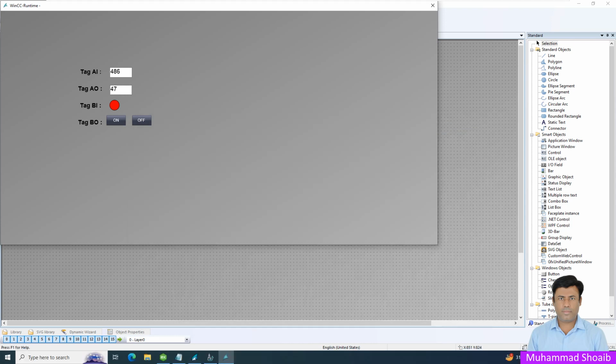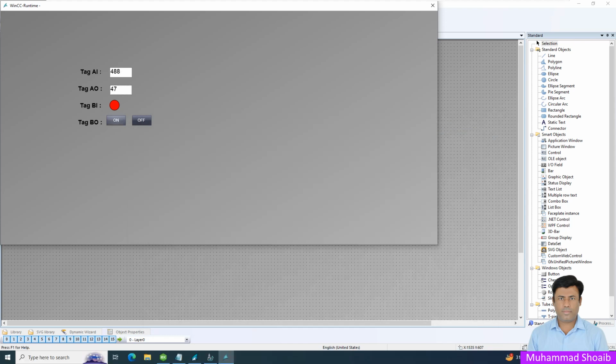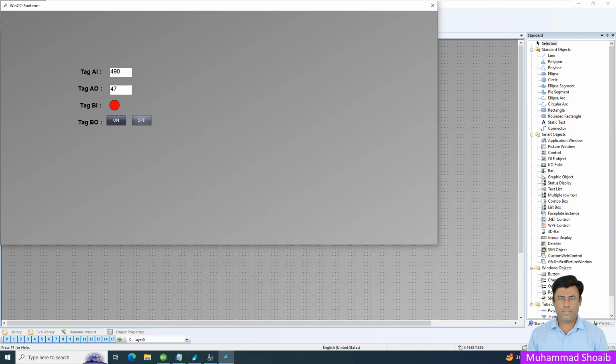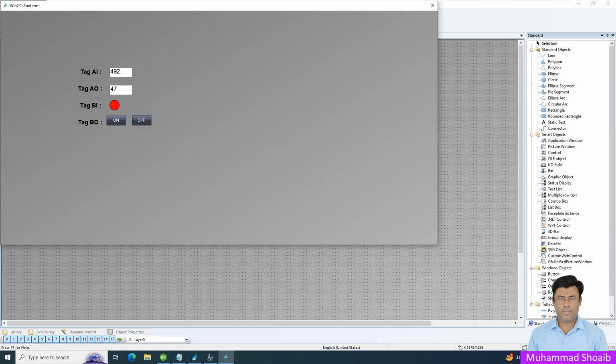Okay, perfect. Now what about our command signal, the binary output signal? Right now this signal, tag DO, is showing 0. I will send this true command, and as you can see, I receive this true value here. If I send the false command, as you can see, the command also has now become false.